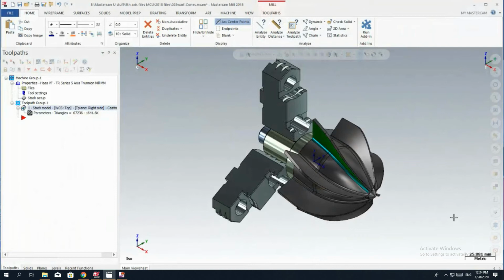In this video, we are going to start looking at the 5-axis toolpaths. So we are going to start with a multi-axis pattern style path called swarf milling. Swarf milling is sometimes called flank milling, as both swarf and flank milling is a toolpath that uses the side of the tool when cutting.